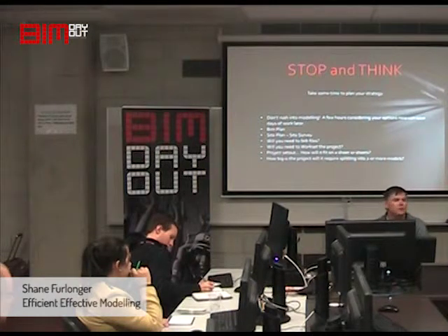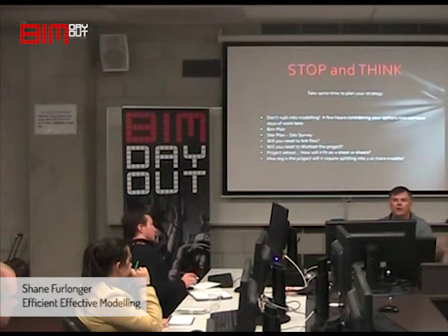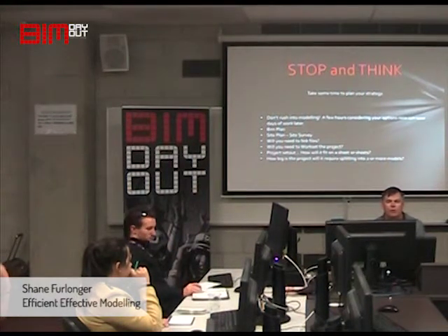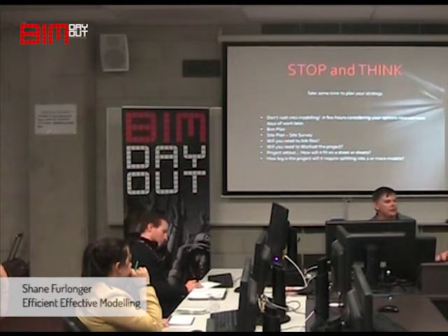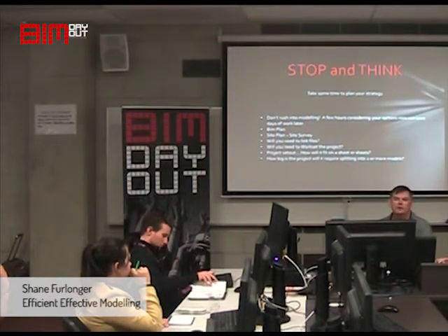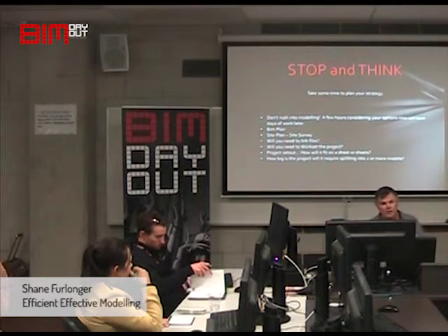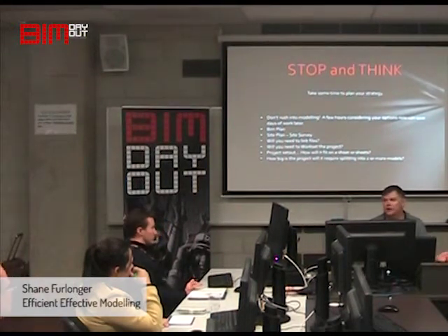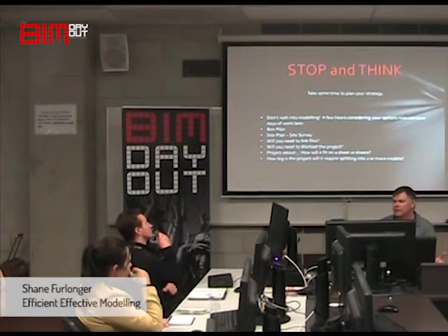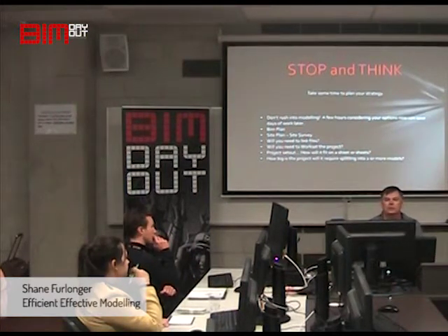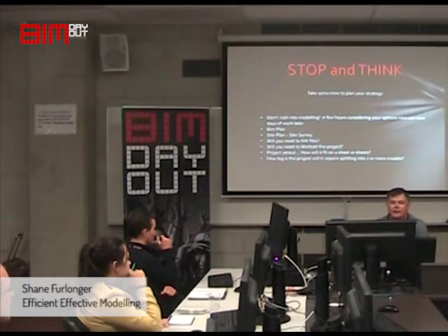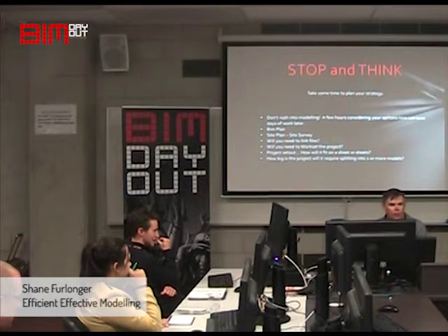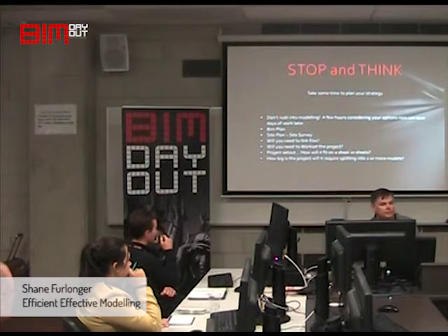What do most of the people here use work sets for? As a tool to turn on and off like a layer, because the original idea of work sets is gone. Work sets were originally for grabbing hold of a piece of work and working on it. That no longer is relevant because of the way Revit now works, but it is still a good process for breaking your model up for not loading stuff.